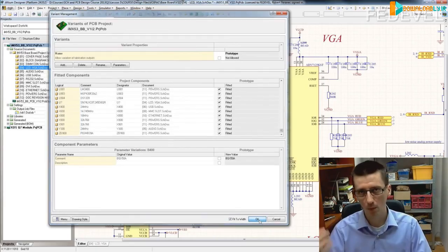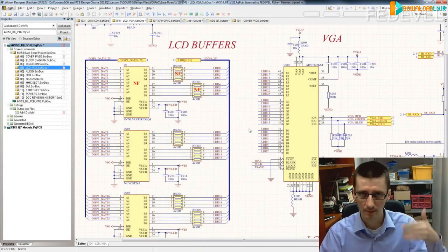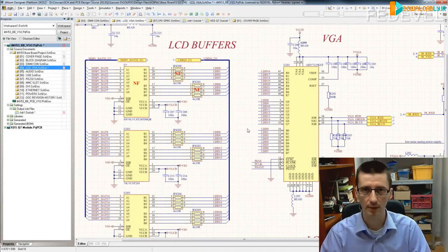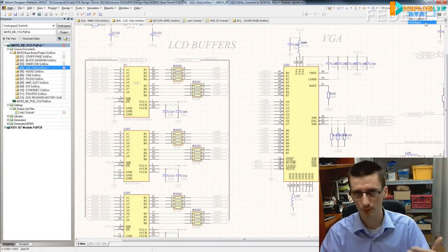You have more options for how or where to configure the variant. The visual way is doing it this way. Maybe you never spotted, on the bottom of the schematic there are two tabs. Now I will click on the second one. I go to the variant manager and I select our prototype variant.